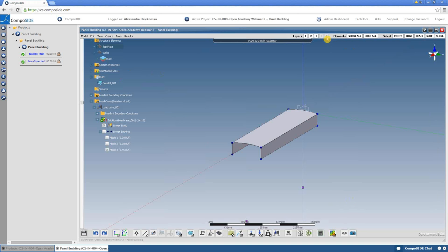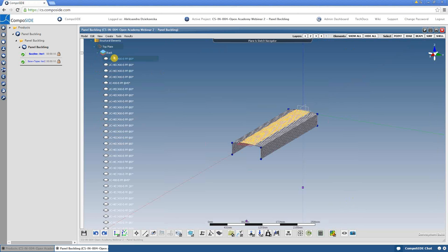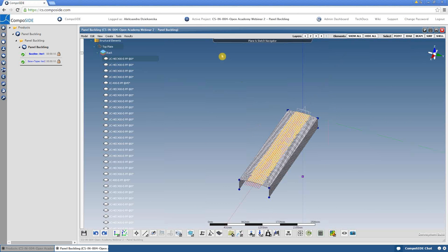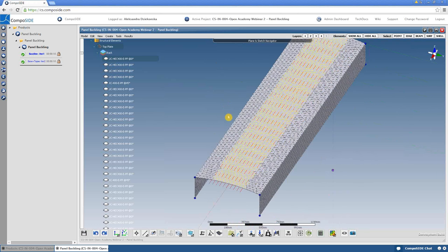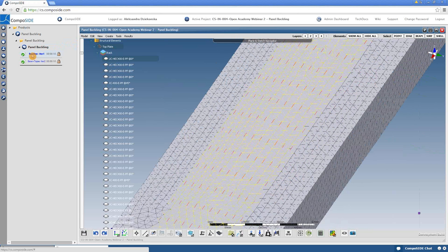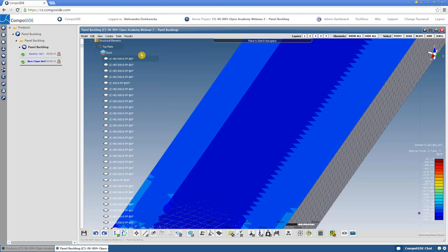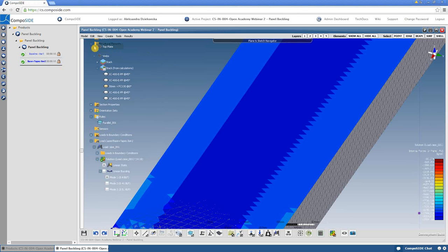If I show you the mesh, we're going to quickly see that only those elements will be using those additional tapes. You can create local reinforcement, you can limit the extent of your plies by using simple rules. It's very, very quick to do, and to iterate through your design. You're going to see in the next examples how we do it in practice.